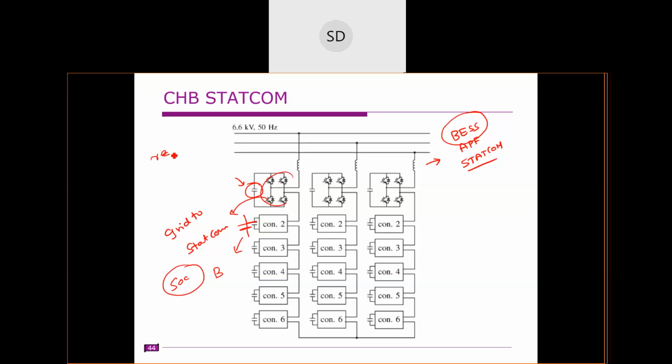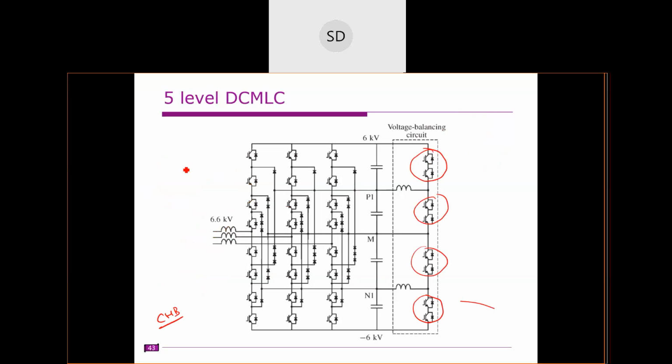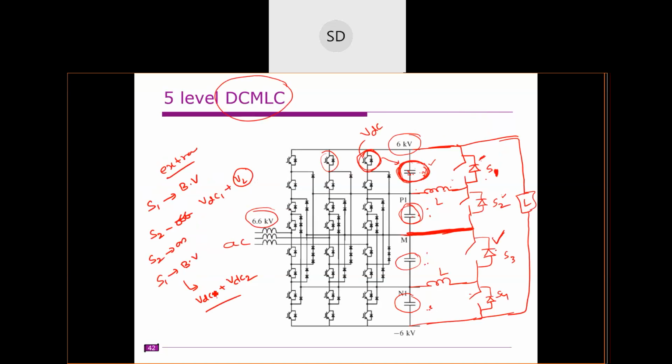Okay, right? So how will the real power actually flow? We might have studied this. If there are two buses, how does power flow from one bus to the other bus? There must be some angle difference. Whenever there is some angle difference between these two, a power flow will happen. That is how the power flow happens, right? You might have studied those power curves.